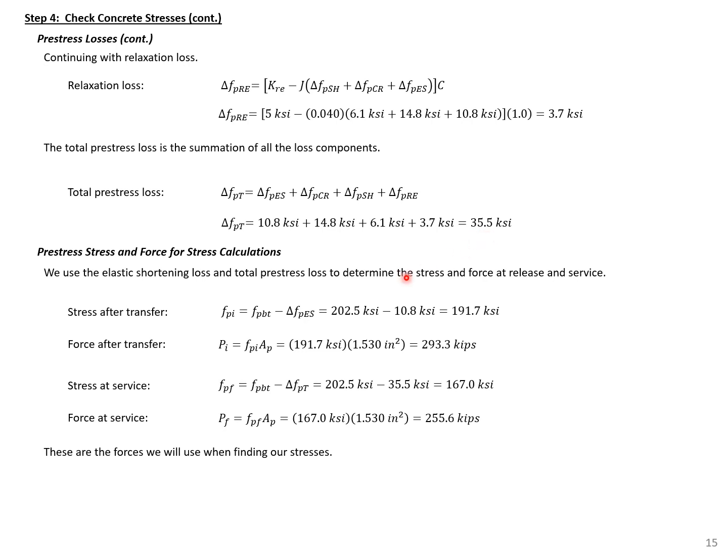We'll need the force after transfer and the force at service in our stress calculations, so that's what I'm finding here. The force after transfer considers the stress after elastic shortening times our total area, and the force at service is our service stress after all pre-stress losses times our area. So we have those two values there, force after transfer and force at service.